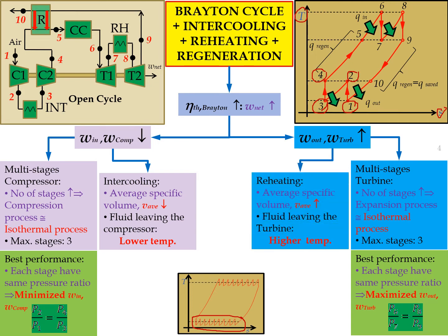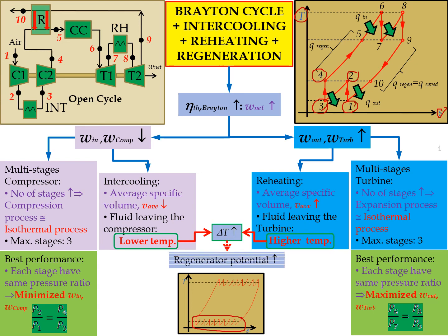Same with the compressor. The function of reheating is to increase the average specific volume, and it also increases the temperature of the air that goes into the next expansion process. So it increases the temperature difference here, and also increases the regeneration potential.